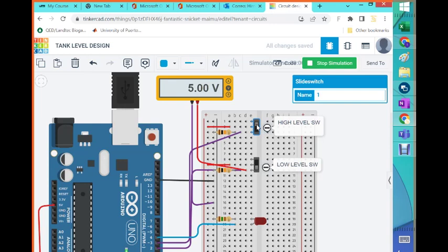So it's working. Now, what's going to happen is that this one will open as well, because the vessel will drain totally. So the pump should start. If not, the code is bad. Bingo. What I'm doing right now is testing the code. It's called validation: ensuring that the code does what it's supposed to do. We create a truth table.